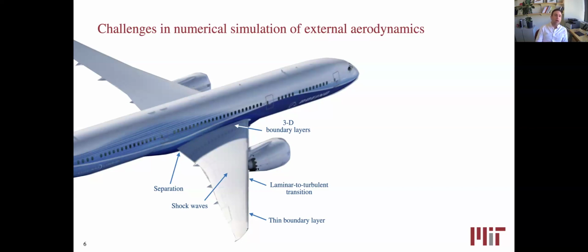It's not so simple. Related to separation, the model tends to capture separation okay. The reason is that most of the large scales are resolved by the grid of the large eddy simulation, and the model only needs to account for the smallest scales. So if there is something that is a large scale trend, the model will capture that. If the smallest scales are what is missing, and those are smaller than the typical geometry of the problem, then the model will do a good job.